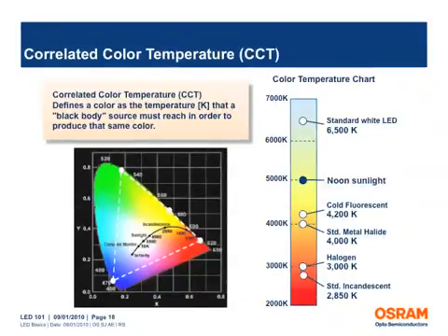The correlated color temperature is the temperature at which a Planckian black-body radiator and an illumination source appear to match. It is usually specified in degrees Kelvin. The CCT for a light source gives a good indication of the lamp's general appearance, but does not give information on its spectral power distribution. Therefore, two lamps may appear to be the same color, but their effects on object colors can be quite different.